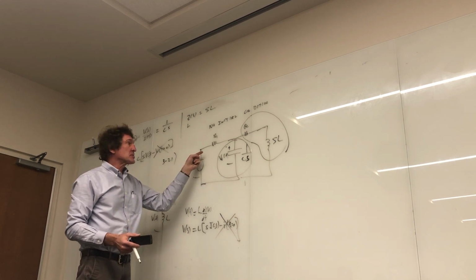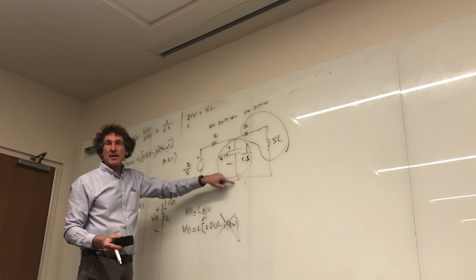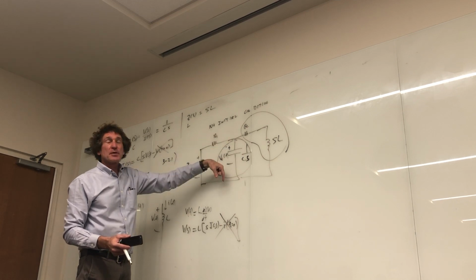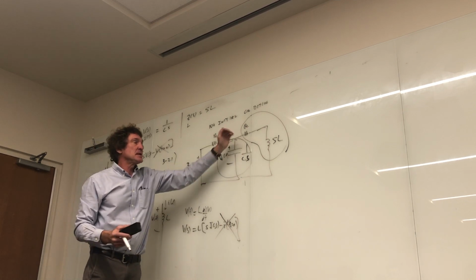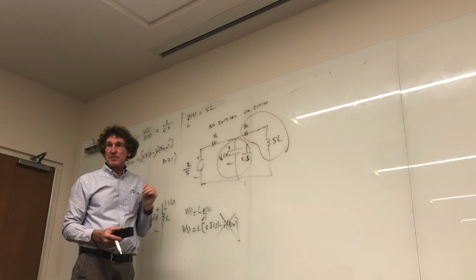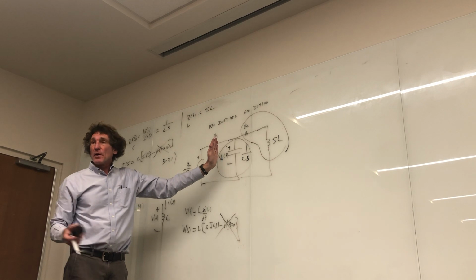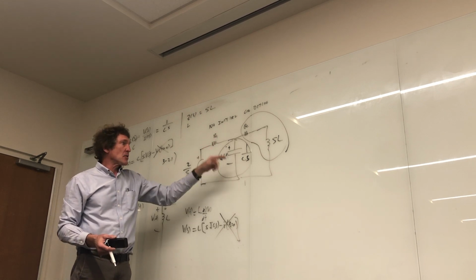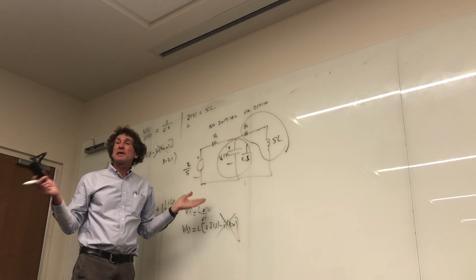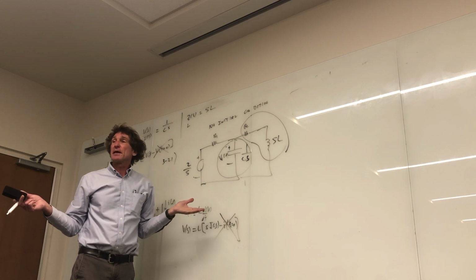And then I'd say, well, that current's going to split when it hits this node. And I can figure the amount of current that goes here because I take the opposite impedance divided by that plus this impedance and multiply by the current. And now I have the current there. And when I wanted the voltage, I'd multiply the current by the impedance, which is 1 over CS, and I'd have the voltage. That's one way to do it. You get the right answer.